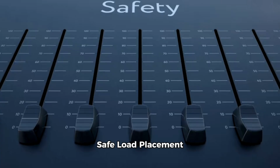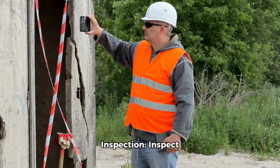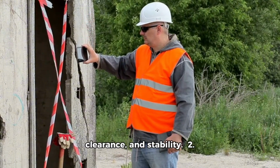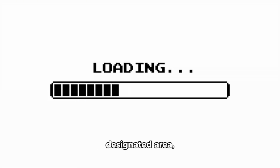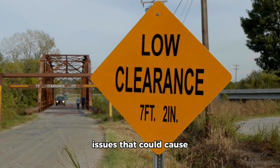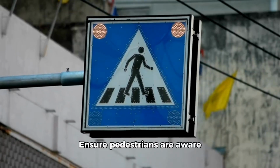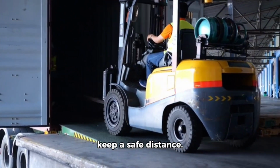Safe load placement procedures. 1. Destination inspection. Inspect the destination area for obstacles, clearance, and stability. 2. Load placement. Place the load in the designated area, ensuring it is stable and secure. 3. Clearance and obstacles. Ensure there are no obstacles or clearance issues that could cause the load to shift or fall. 4. Pedestrian safety. Ensure pedestrians are aware of the forklift's presence and keep a safe distance.